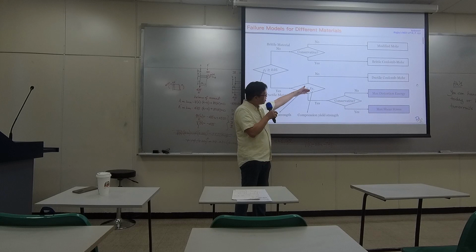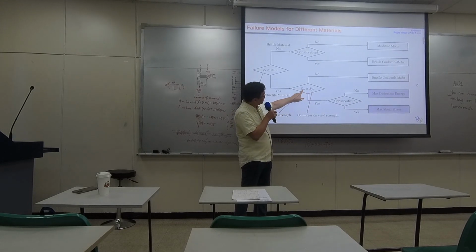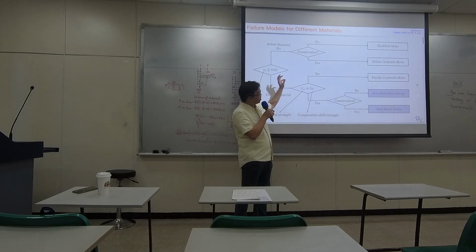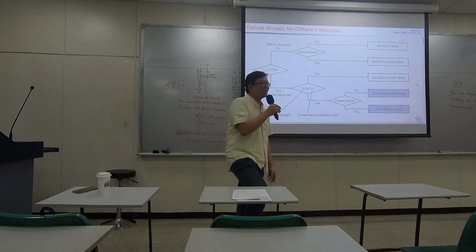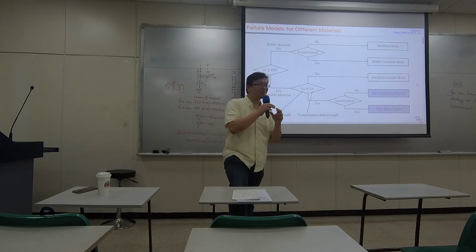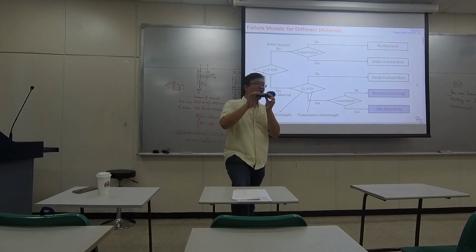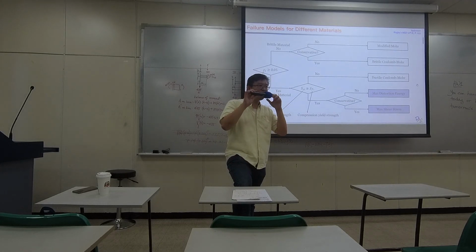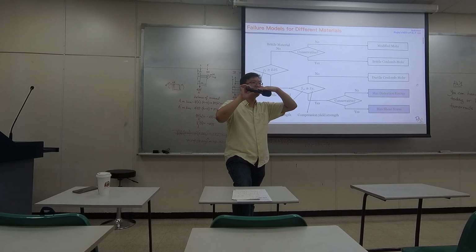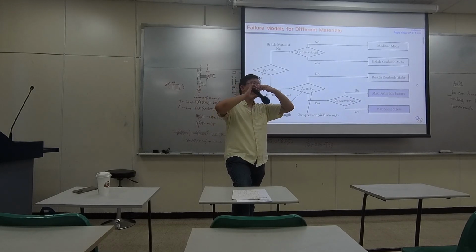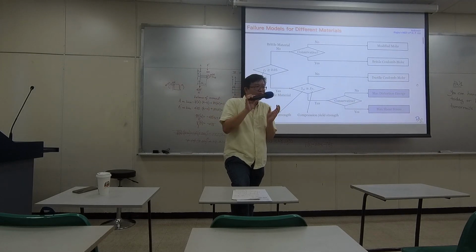Why do we specifically want to study a kind of material that has similar yield strength on tensile and compression? Because that's easier to analyze. For example, if I have a shaft, I'm bending it. I know if I bend this way, the upper edge is in a tensile situation, and the bottom is in compression.